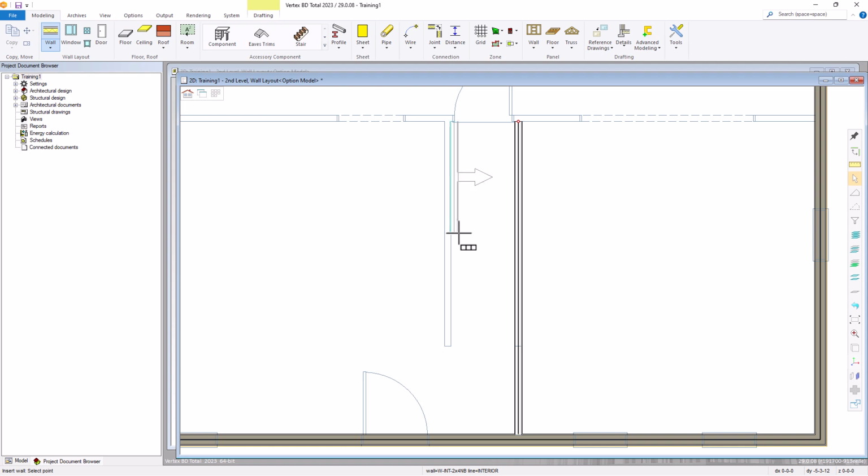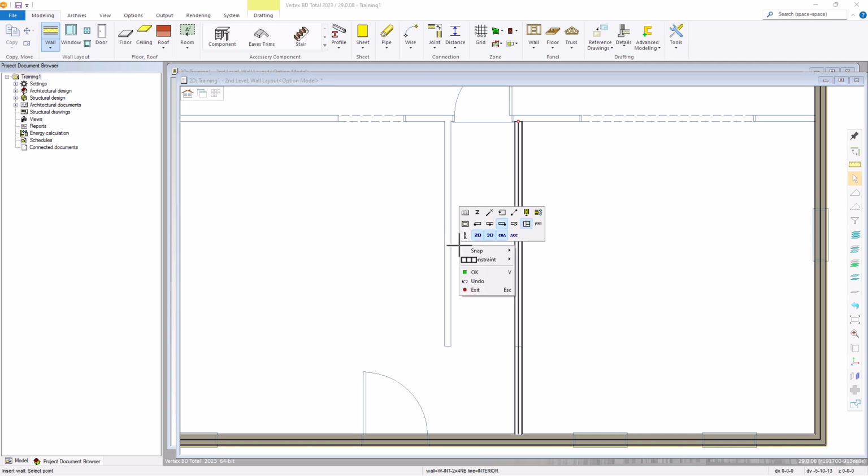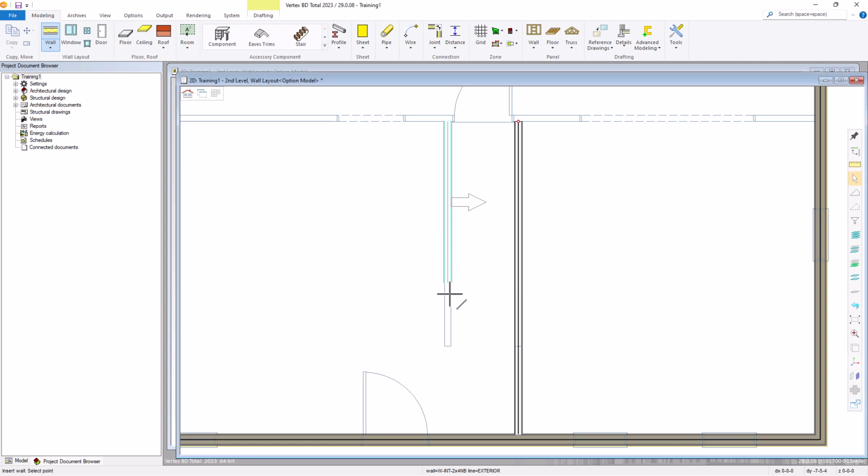Lock it in the vertical with the I key. Adjust the wall placement to line up the wall with the reference wall below. And let's just turn the corner there. Hit the U key or the X-axis constraint and butt up against that wall. And V to confirm.